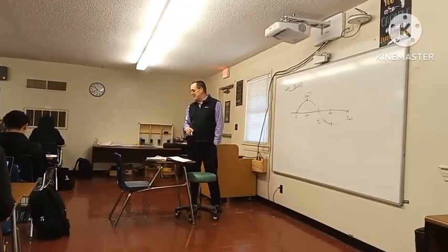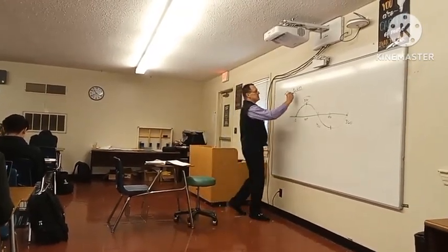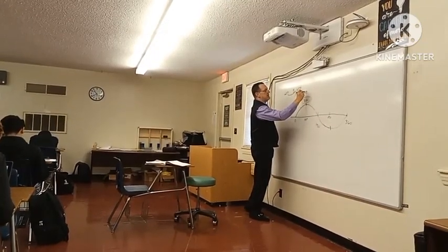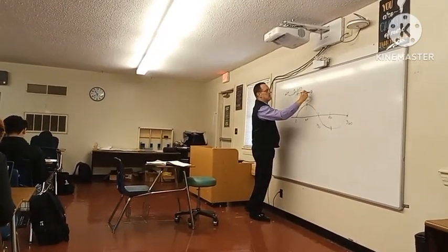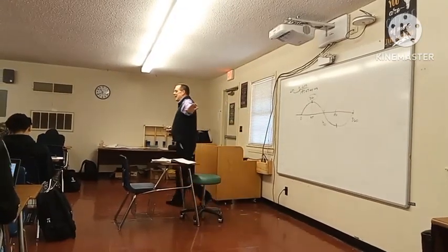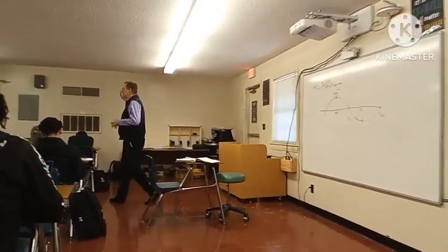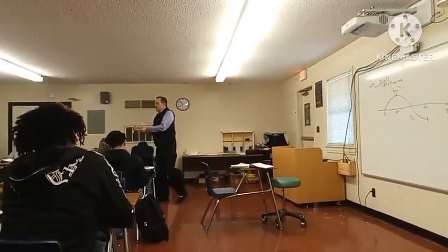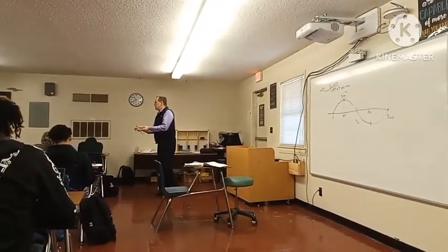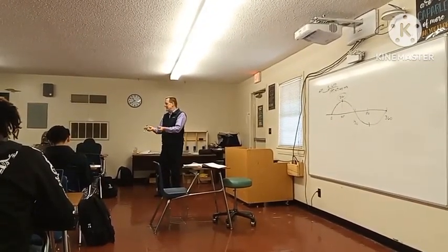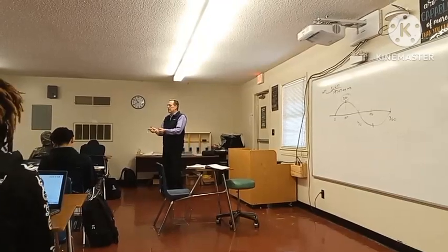197.47? Right. That would be the average voltage. That means if you came to this circuit, forget about the peak voltage, if you were just testing the voltage on it, the reading that your meter's going to give you is going to be what? Are you going to read that 310 or are you going to read 197? You're going to read 197.